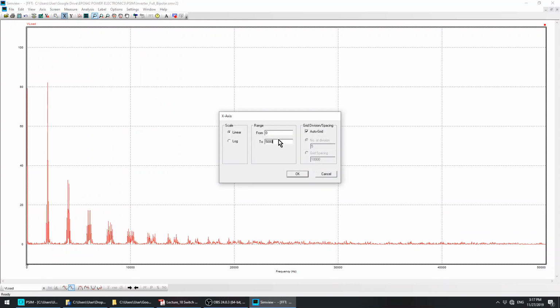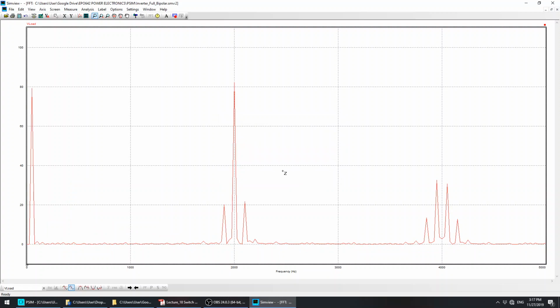That is the switching frequency, then the fundamental, and the amplitude of the fundamental component you can calculate using M multiplied by Vin. So M is 0.8 multiplied by Vin of 100, so you get almost 80 volts, right?